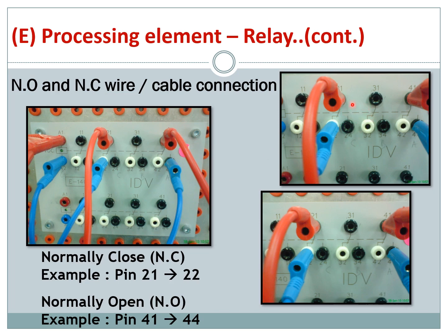You can see here you have a few ports: 11, 21, 31, 41. So it has a numbering. For normally closed, or NC, we normally connect pin 21, or whatever number that ends with 1, to the number ending with 2. So you have a few connectors or circuits that you can utilize. And for normally open, we normally connect the pin starting with 1 to the pin ending with 4. Like you can see here, you have 14, 24, 34. So you can make the connection.